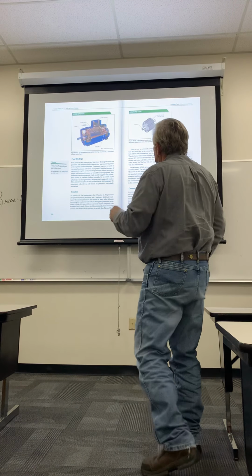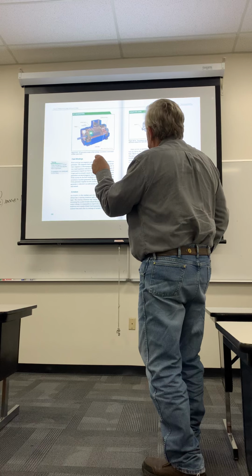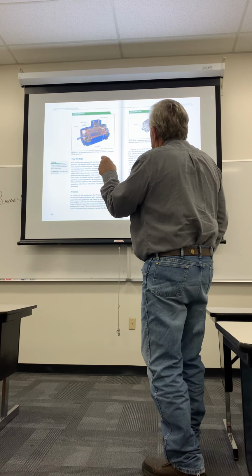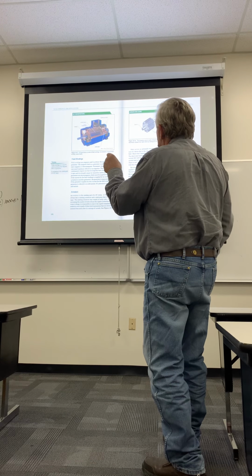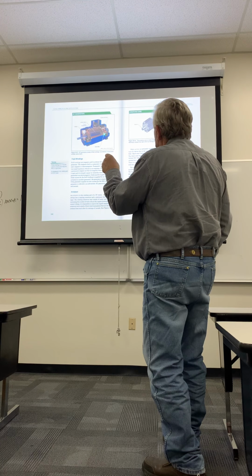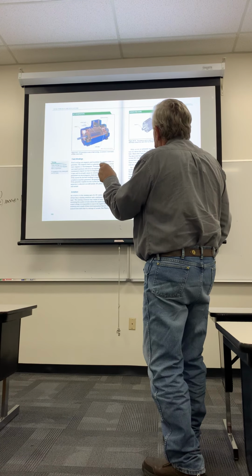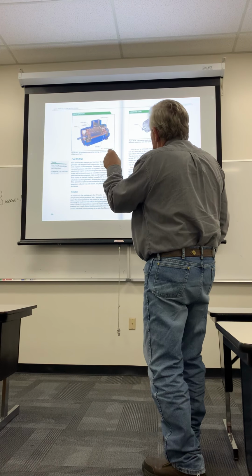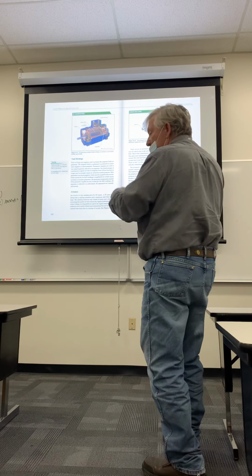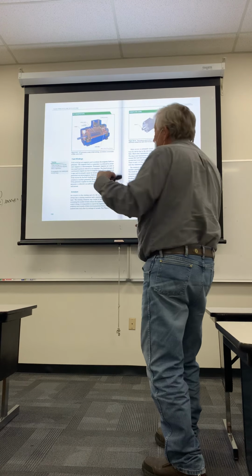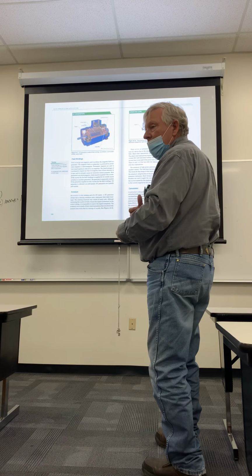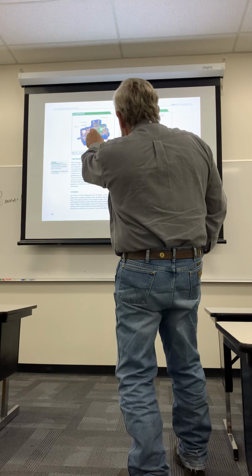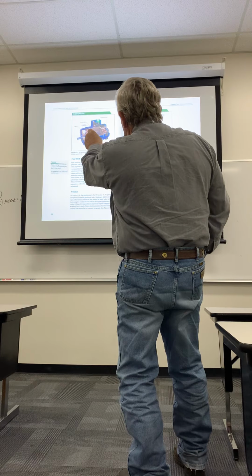And there's a certain number of slots in the armature that have electrical wiring in them. They're wrapped around back and forth all the way through to create this armature that as it spins, breaks that magnetic field, and then that current is carried to the back part here, to the commutator.